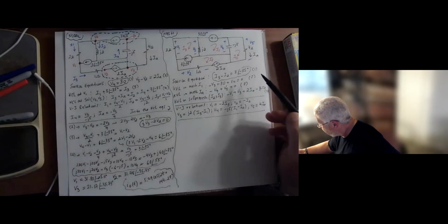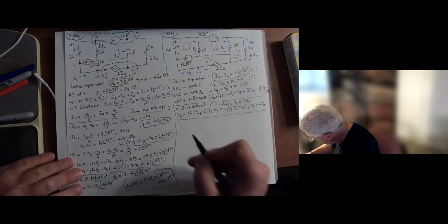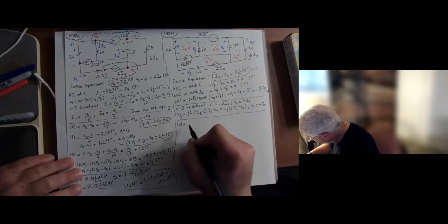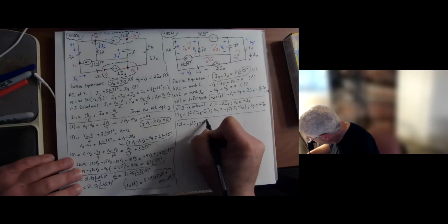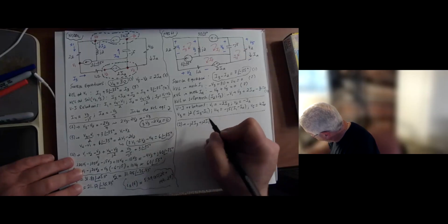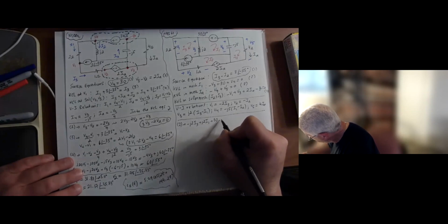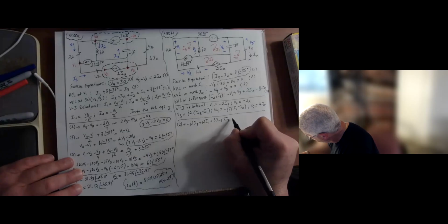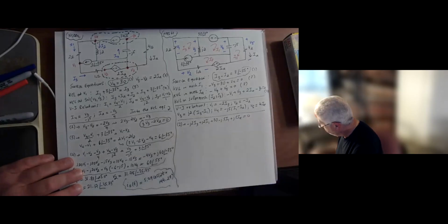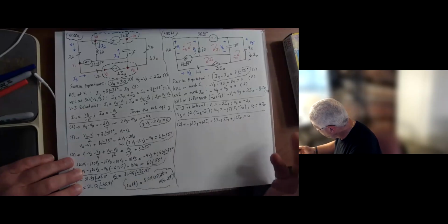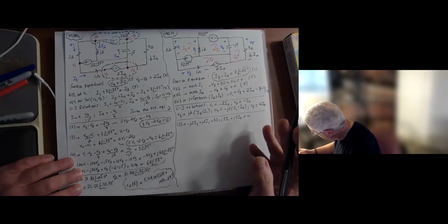Obviously, now I'm going to put them in equations 2, 3, and 4. Equation 1 really is a done equation. So equation 2 becomes minus V3, minus J2I3 plus J2I1, plus 30 plus V4, minus J5I1 plus J5IA equals 0. I can send the 30 to the other side and then collect terms here.